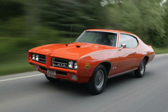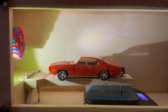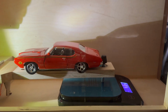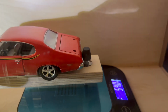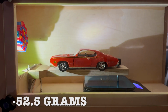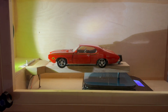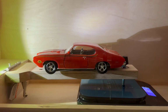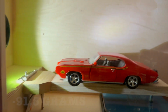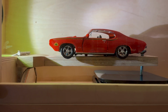Finally, we once again repeat the experiment, but this time we are using winds that are 180 miles per hour. Our first experiment shows that without the spoiler, the average weight for 180 miles per hour is negative 52.5 grams. Next, we have the same experiment, but without the laminar flow of the straws, and that's about negative 91.5 grams. As you can see in this video, the car starts to lift up since there is so much lift acting on the car.